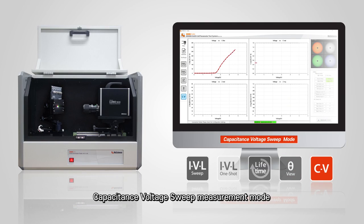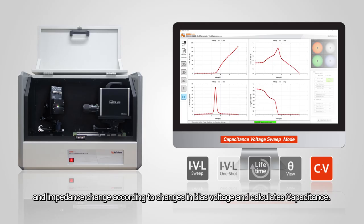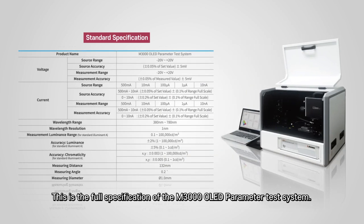Capacitance voltage sweep measurement mode measures the impedance response characteristics according to voltage change at the set frequency, and the impedance change according to changes in bias voltage, and calculates capacitance. This is the full specification of the M3000 OLED parameter test system.